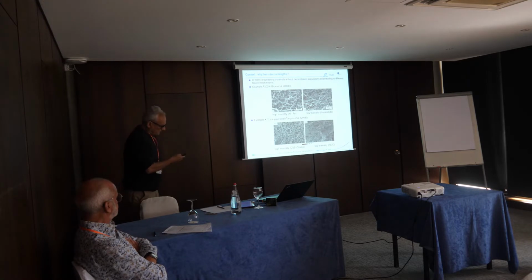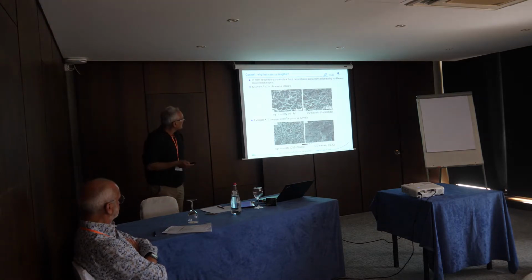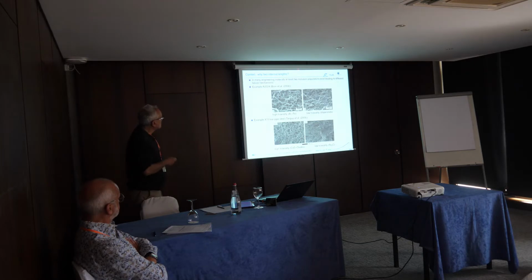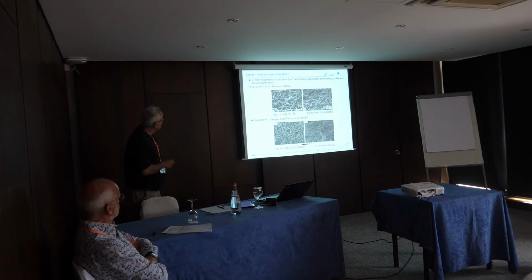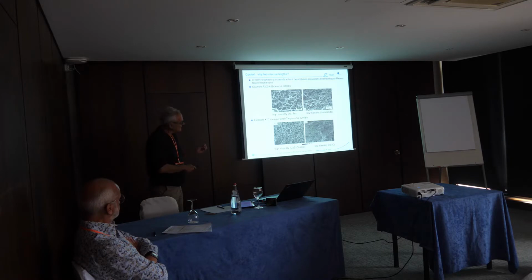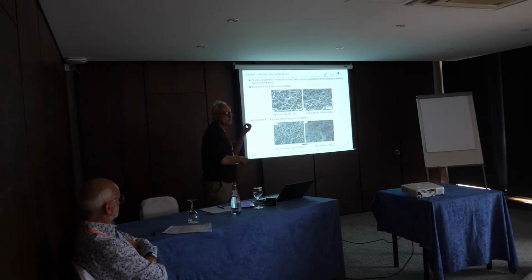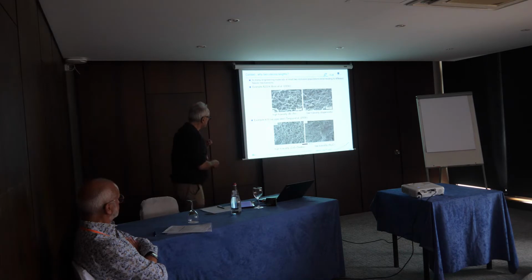Why two internal lengths? If you look at engineering materials, you very often see two inclusion populations that are at the origin of fracture. Here's an example with a standard aluminum alloy. At high triaxiality, I get fairly large dimples, which are initiated on particles containing iron. At lower triaxiality, and note that the scale bar here is exactly the same, I get much smaller dimples, which are initiated on very small dispersoids that are there to strengthen the material.